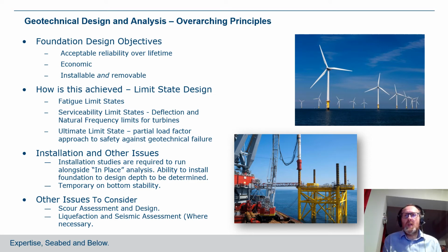So we look at ultimate limit state, so the set of worst case loads, and check that the foundation will be suitable, that there'll be no ground failure and that no catastrophic collapse will occur. We then look at normal loading conditions, serviceability limit states, and check that deflections and natural frequencies of the combined system are within the limits for the turbine. And then thirdly, we look at fatigue limit states, which are lower levels of high numbers of cycles of loads, to check that structural components won't be subject to fatigue damage with constant beating of loading on the structure.